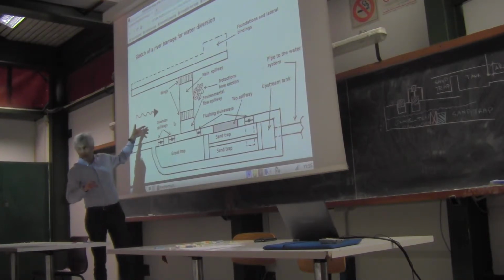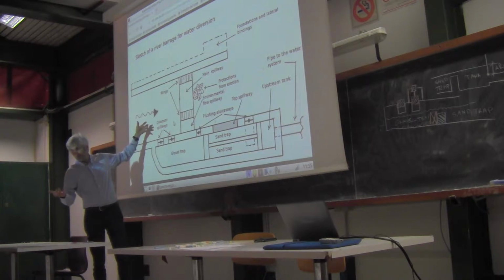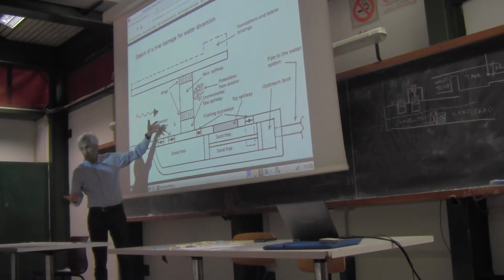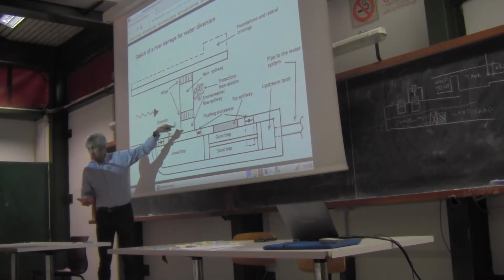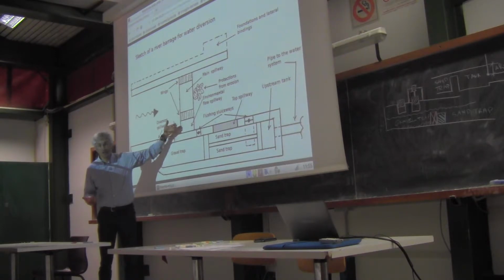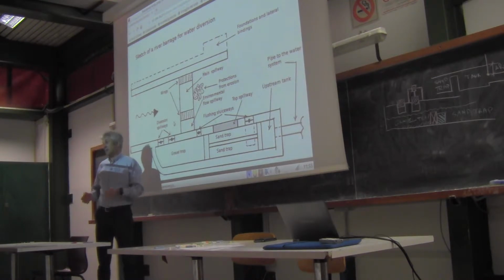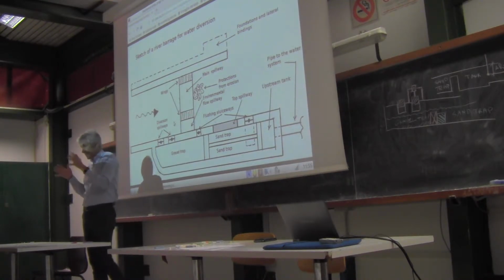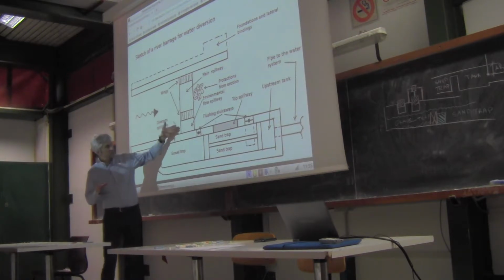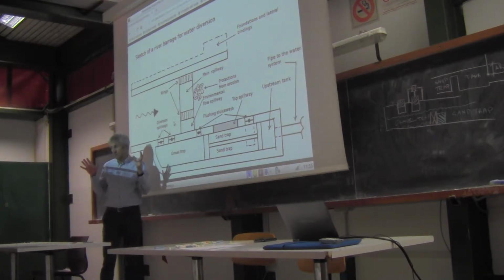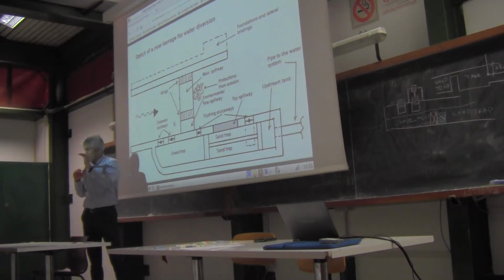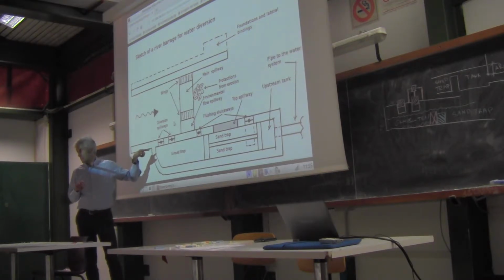If water continues to increase the flow from upstream, we observe a continuous increase of the water level in the pool and over the spillway, and we observe a corresponding increase of the flow, the environmental flow through the spillway. At a certain stage, we will reach, finally, the desired value of the environmental flow over the spillway. When water is at that level, I can start diverting some water, not before.